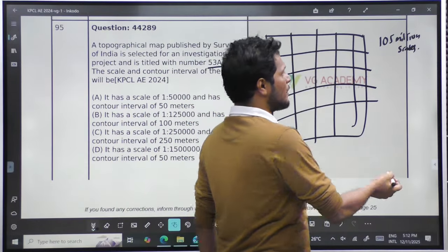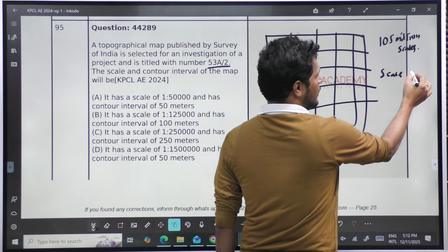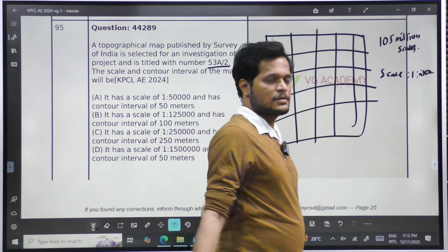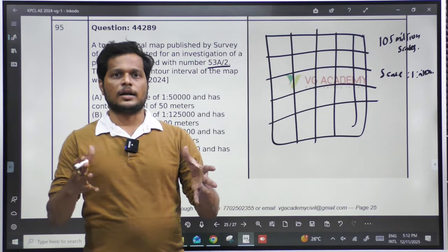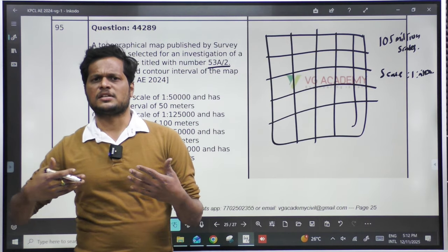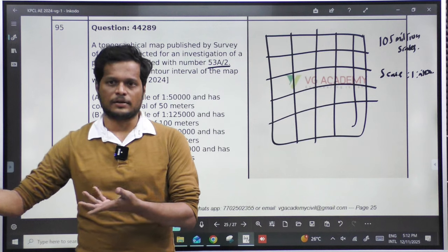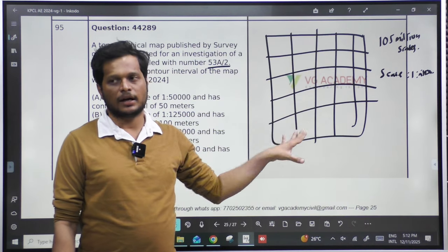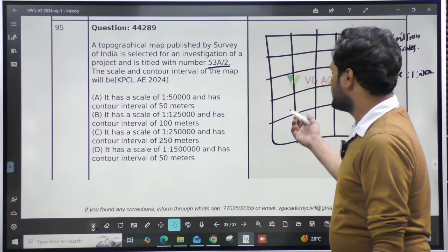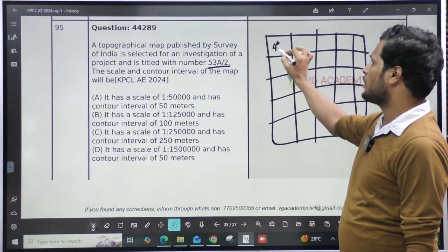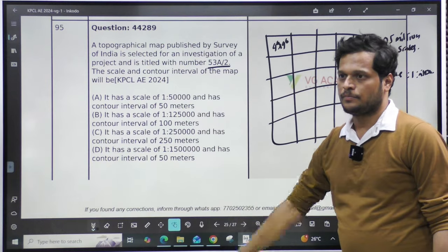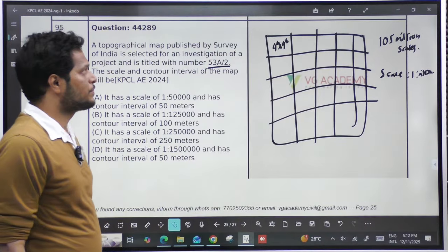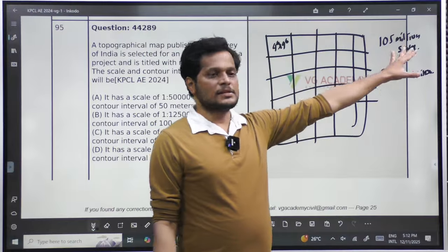What does this million scale map mean? Scale is 1:million. Our country is so big that Survey of India regularly publishes these maps. You will be buying state maps like this, different maps will be published. Our country is divided such that each grid will have 4 degree by 4 degree. These are called million scale maps. There are 105 million scale maps in this.